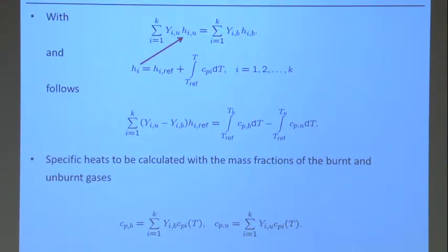This would be the fuel and the oxygen, or the oxygen is 0, but the fuel is high. And then these are converted to CO2 and H2O, and they are strongly negative. So this energy that's stored in the bonds, from fuel and oxygen to products, will go down. So this reference part, the chemical energy, goes down through the combustion process.